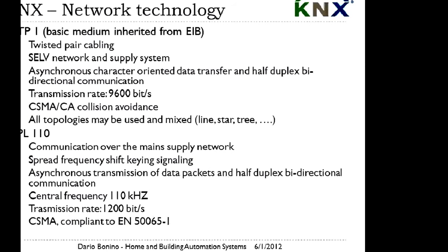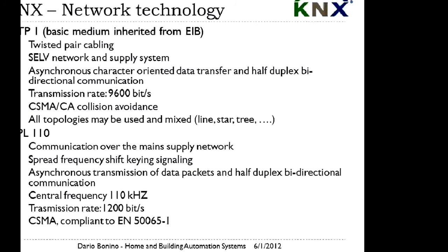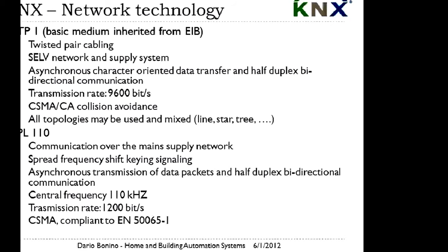That means everyone accesses the bus, but before they start transmitting they check, and if someone else is transmitting, there is a change on the bus level, basically, and this change is detected, and the devices stop transmission and try to retransmit after some time. Okay, so one single bus. This is the same access method used on the Ethernet networks. Okay.